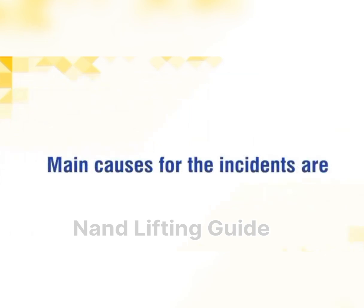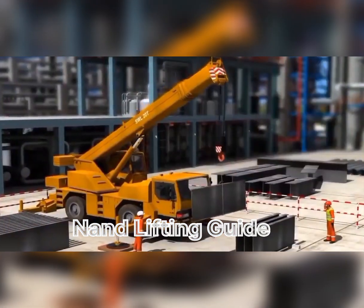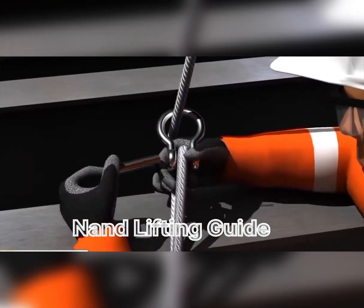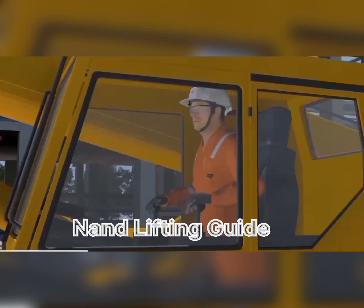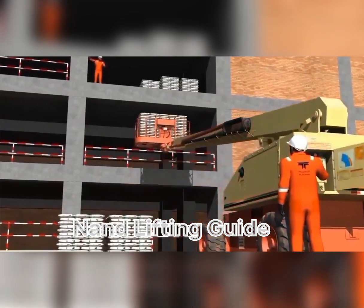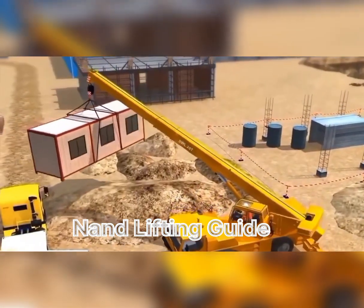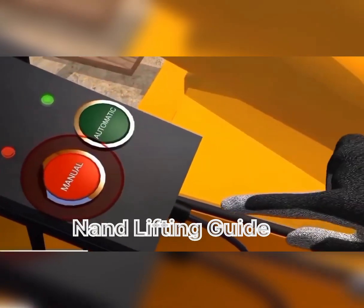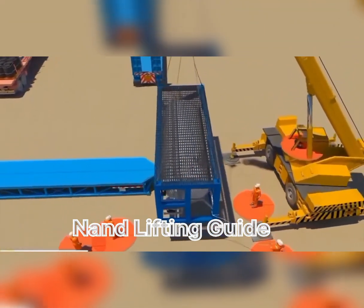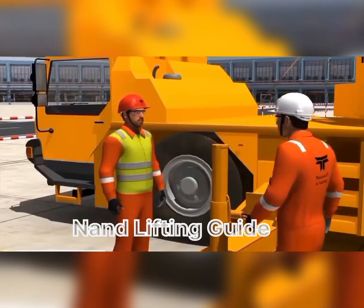Main causes for the incidents are defective wire rope sling, violation of the set procedures, such as not using the lifting plan, poor risk assessment, incompetent crew, using MEWP as a lifting equipment, overriding the safety controls on the lifting equipment, people being in the line of fire, person getting struck by and caught between dead weight and outrigger,